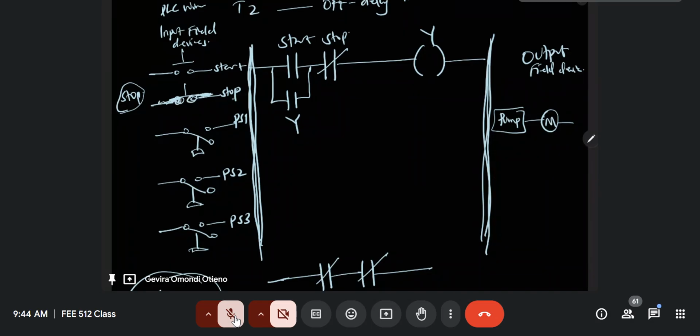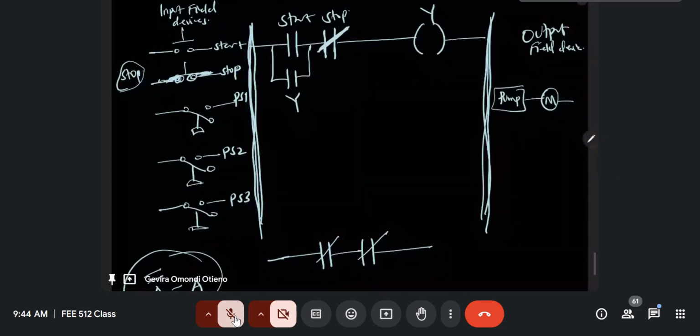So then if you represent it again with a stop, a normally closed contact like this, then the PLC processor, if you operate the entire system, the logic will flow, here it is negated, and again here it is negated. So if you had A here, you're still getting A there. Okay? And therefore, you will not have achieved a stop button.